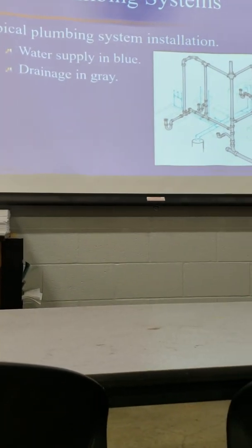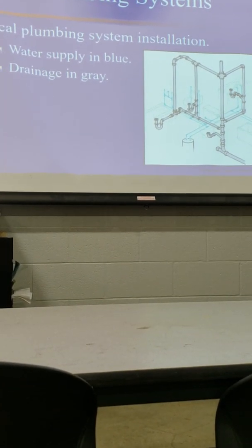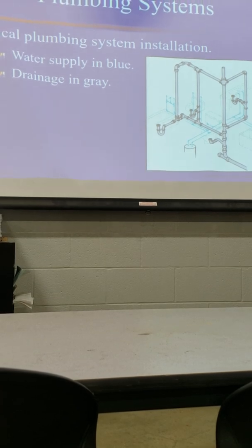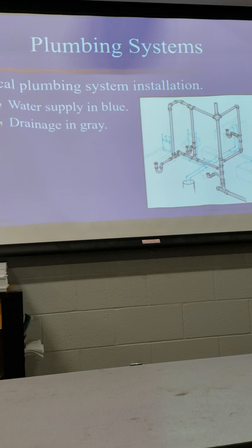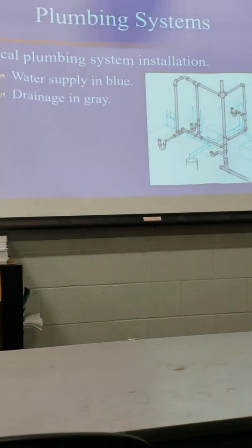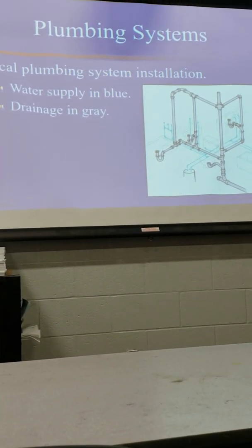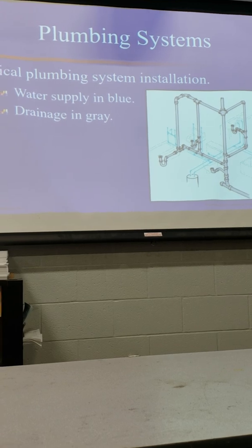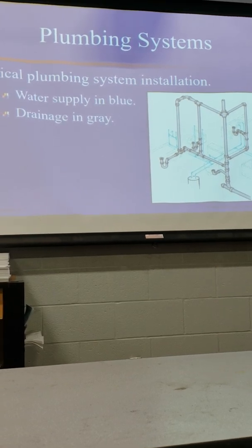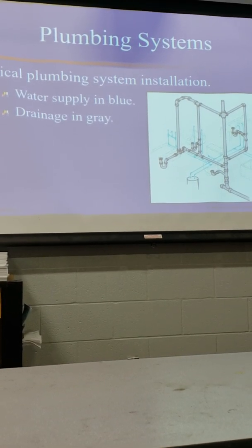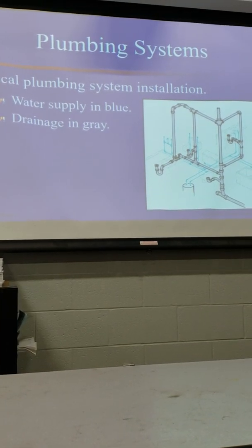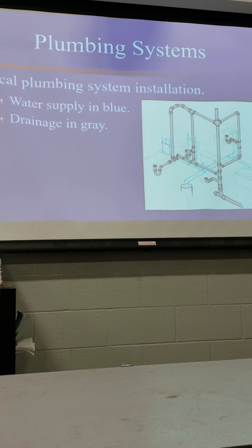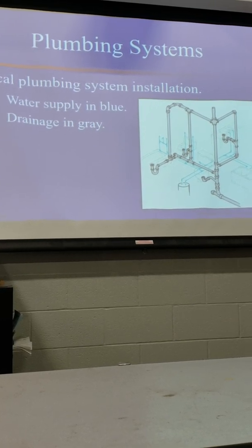That prevents all that air, foul air, sewer gas, whatever, coming back in the house. So if we pull anything out of that, then we're breaking that seal, alright? We'll talk more about traps and how they work and the ways that you can create a trap seal loss. So we'll go into that later.